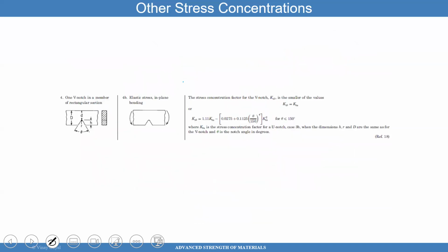Yet another case study. So again, I'm not going to cover each of these cases because in industry, you pull up the book and see which one applies to your case. The point I want to make is finite elements is one way to solve things, but it's not practical because you may have to do calculations that are quite complex when you could have just used a hand calculation that does a fairly good job. Now, if the stress field is exceeding the strength of the material or is yielding, then maybe finite elements may be a better way to go to understand what the effects are from that stress concentration on the nonlinear behavior of the material.